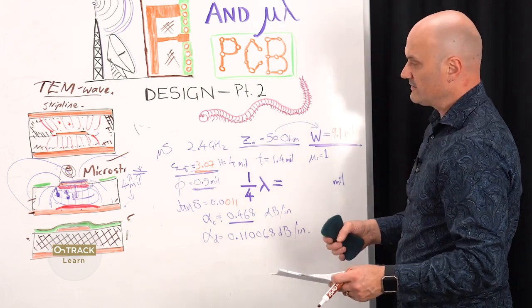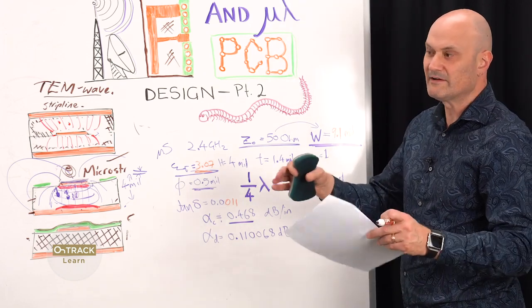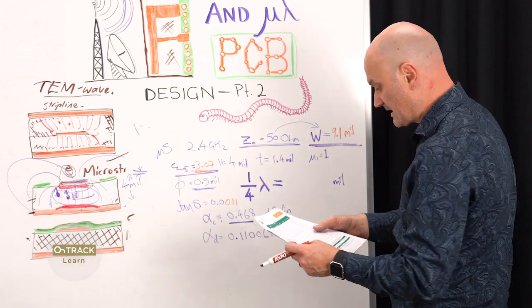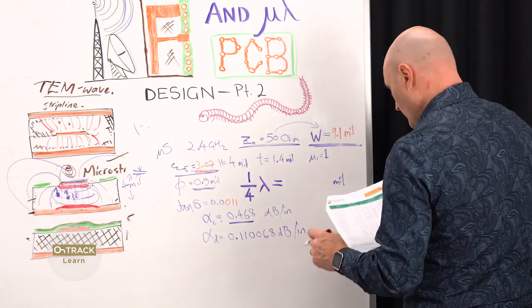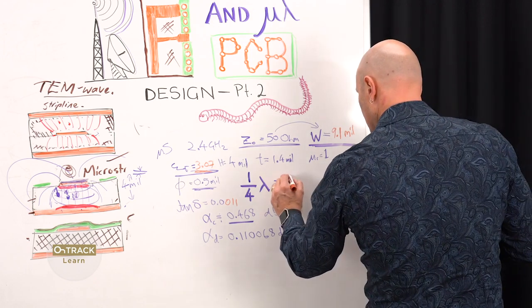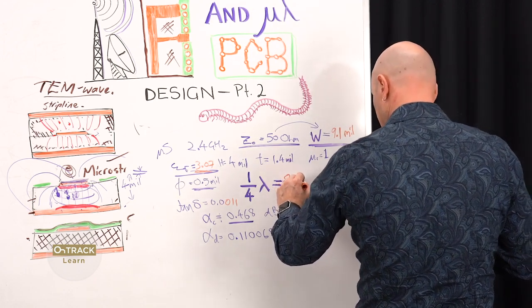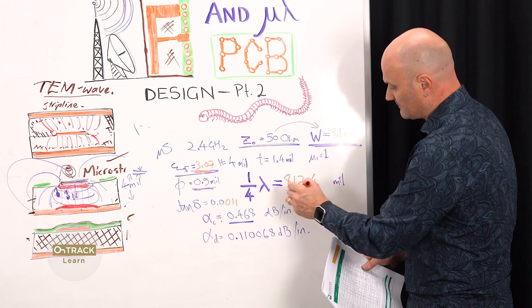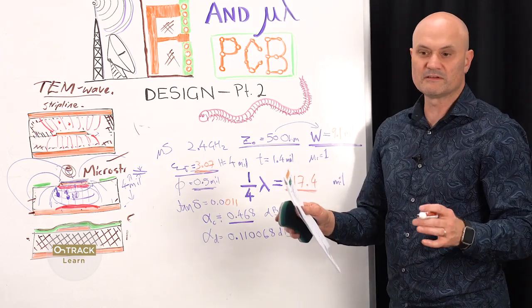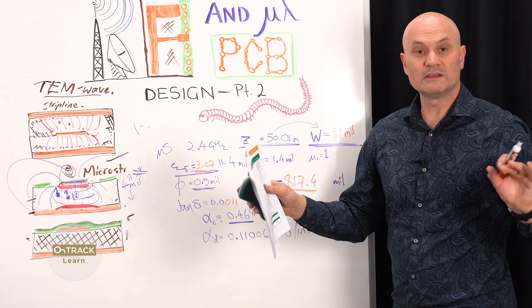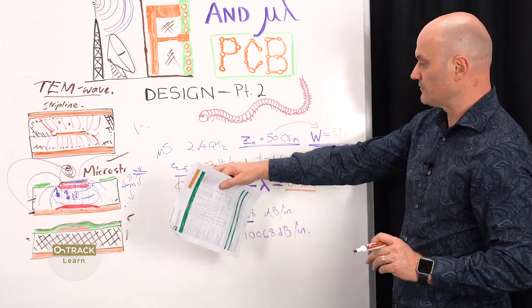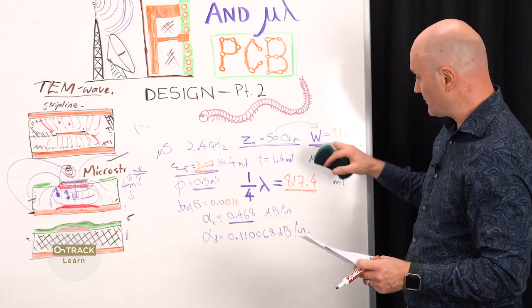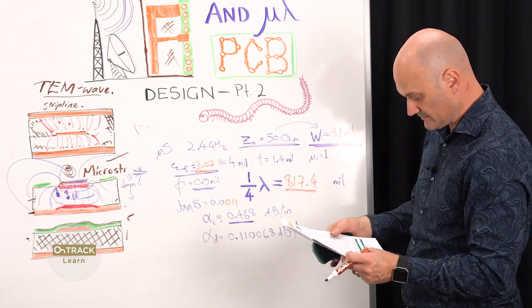This is also typically why air-based antennas have a higher impedance than 50 ohms, and we need to have baluns and things to match them. What else? A quarter wavelength at this frequency is 817.4-ish mils. So the size of our features, things like stubs and filters, they're all increasing. So we need more room. That's maybe a downside of having a lower E sub r: we increase the length of our features and the width for the same system impedance and same frequency.